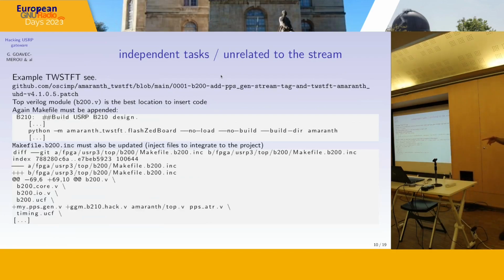Primarily the makefile, because since the gateware, our specific code, is written using the Amaranth language, we had the Python script execution before ISC, because this script produces the Verilog file, and this Verilog file must be known at the launch time, at the ISC launch time, to be integrated into the project.